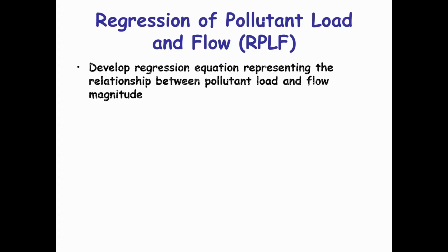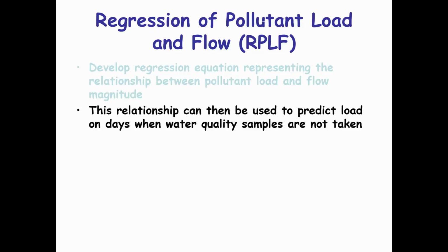The RPLF model or method basically develops regression equations representing the relationship between the pollutant concentration and the flow and magnitude of the flow. In that way, it's somewhat similar to the Flux method, because the Flux method does something very similar to that.